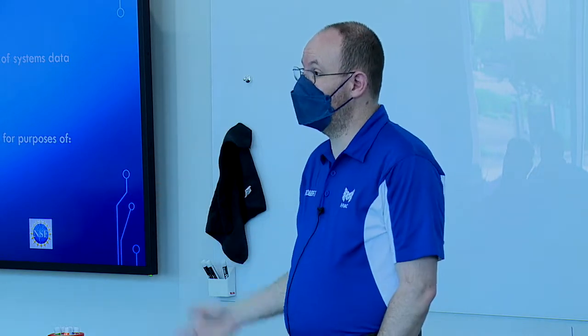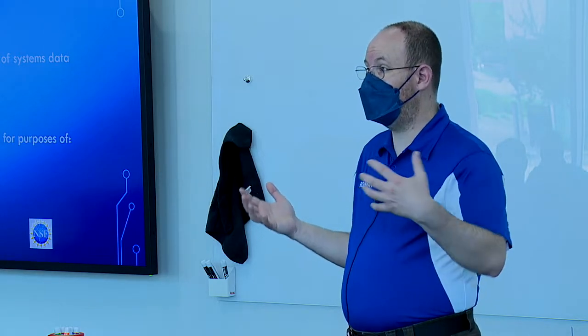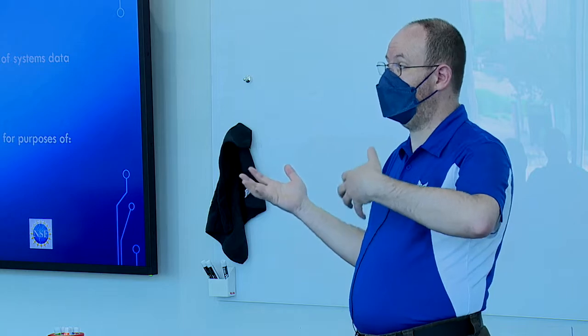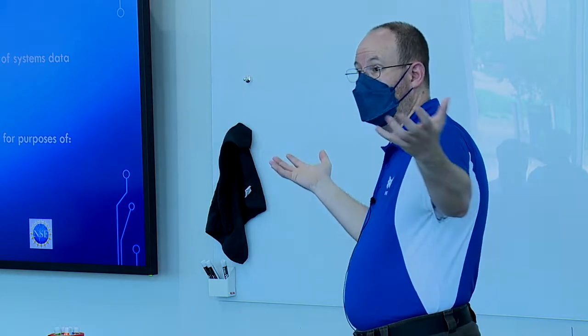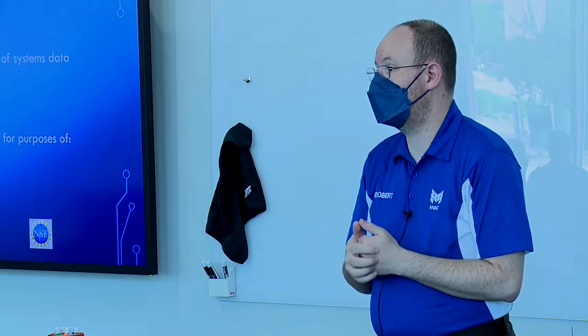I do not disagree with that last statement. Minimize your alarms. Create the alarms you need to have. Using histories is a much better approach. But that is also a conversation you have to have with the people who are going to own and operate the building. You're right. Occupants are going to tell you if they're uncomfortable. Some groups may have the resources to be a little bit more proactive with it and may want to do an alarm on a room. That way they can deal with the problem before the occupants know that it's there.